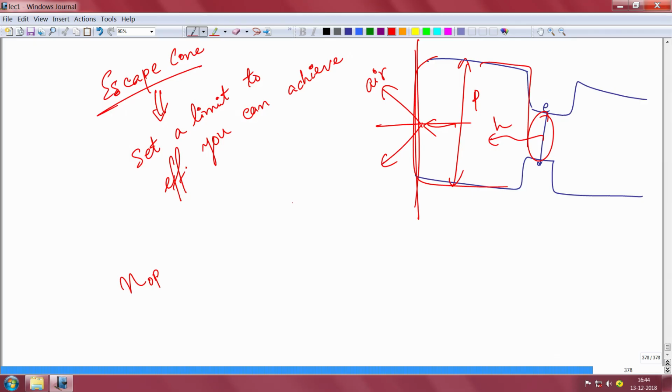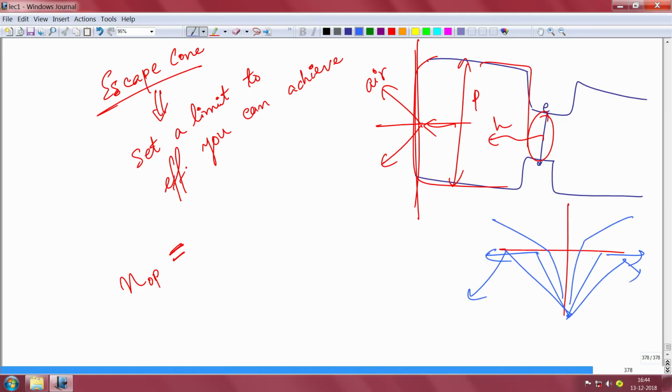So essentially you can think of this as the efficiency that is limited, in that light is coming out within that cone, right. I told you there is a cone there, right. The light can only come out through a cone. After that, light will not come out, after that it will get bounced back. So this cone basically is a solid angle. In 3D you do not talk about a single angle, you just talk about solid angle in steradian, if you remember your 10+2 maths. So essentially that efficiency is limited by this escape cone, because most of the light will get reflected inside and lost, and only a very small fraction will come out.